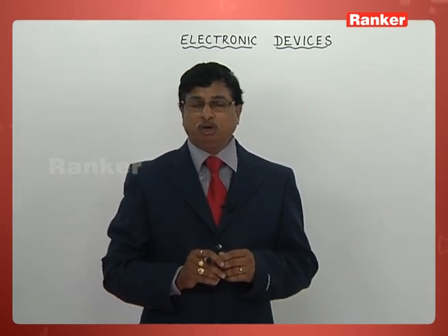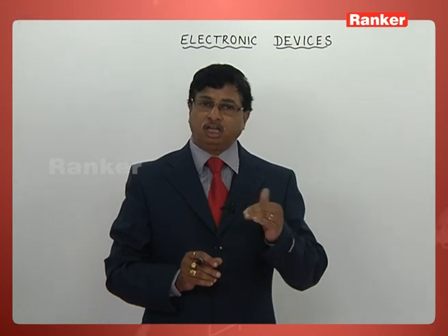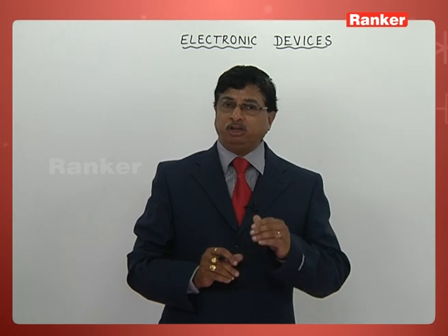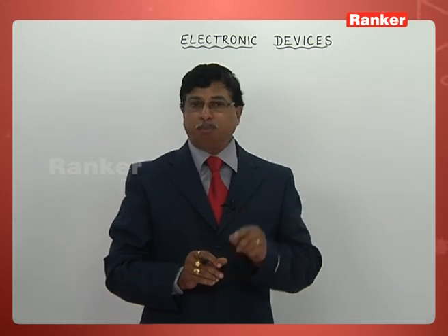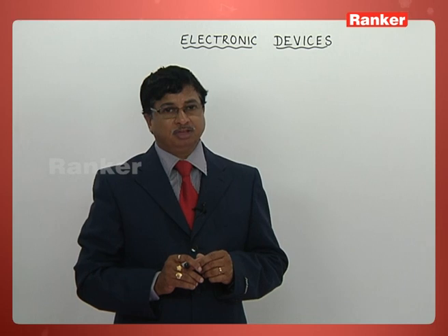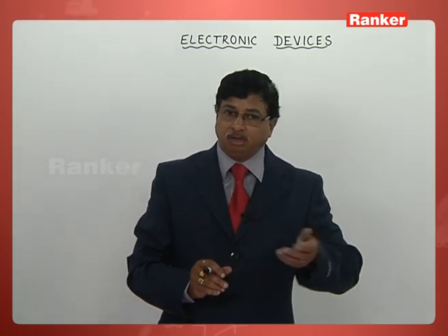In extrinsic semiconductors, while studying that part, one should recollect what is N-type semiconductor and what is a P-type semiconductor. For that also you people all know pretty well. When we dope an intrinsic semiconductor with a third group element, a trivalent element, then we get P-type semiconductor. When we are doping with a pentavalent impurity, then we get N-type semiconductor. So what are the major carriers and minor carriers in these two?